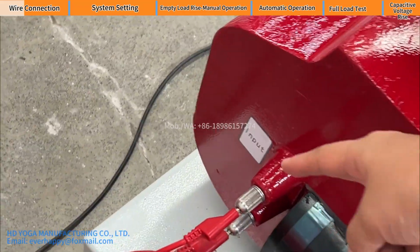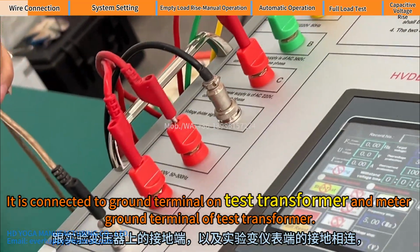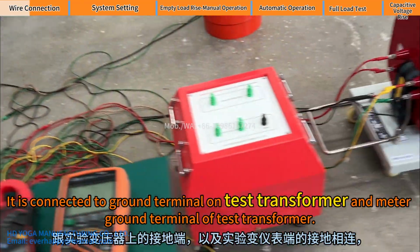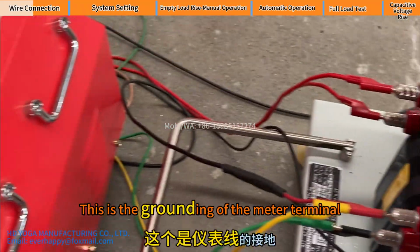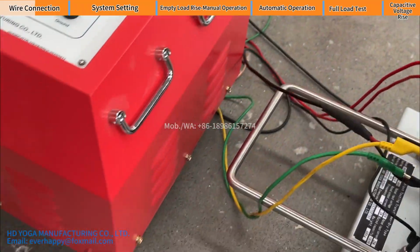This one is the ground wire on the control box. It is connected to the ground terminal on the test transformer and the meter ground terminal of the test transformer. Just connect them all to the ground. This is the grounding of the meter terminal.